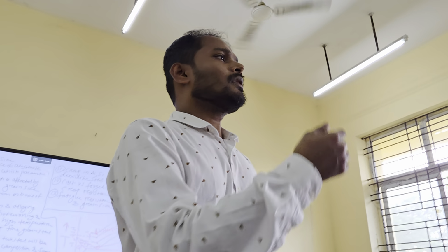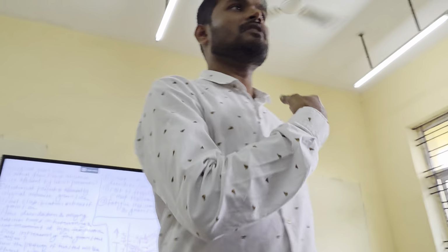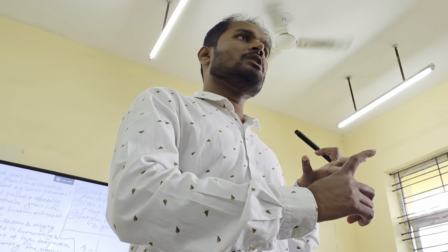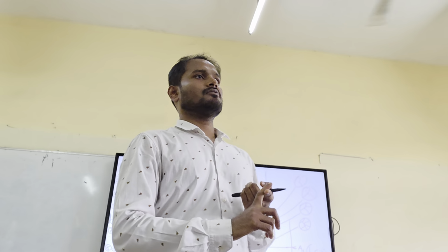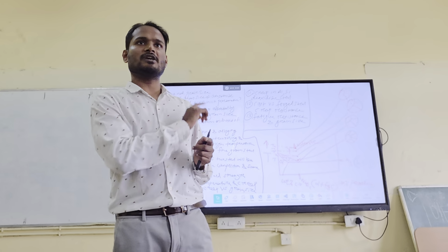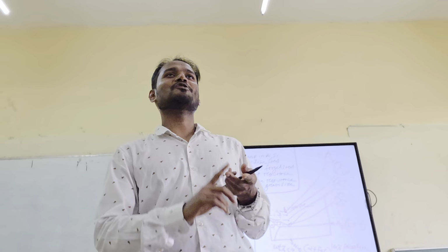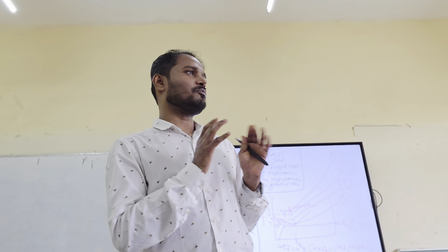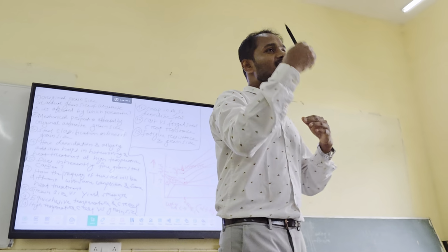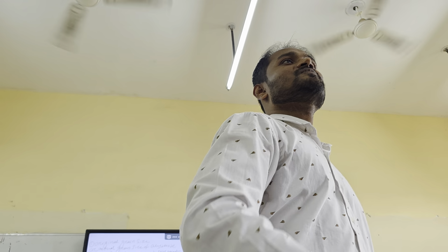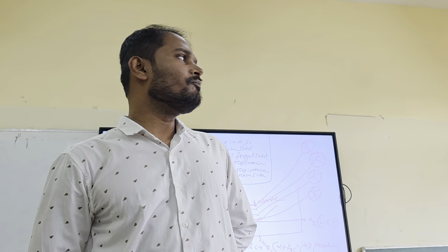Anyways, my point of view is hardenability is a very important property, and that property is affected by the grain size also, austenite grain size. So austenite grain size will affect the strength, it will affect the machinability of the steel, it will affect the hardenability also, and also toughness. These are the 4 important mechanical properties affected by the grain size of the austenite. And we always need good hardenability, good machinability, good strength, good toughness. All should be in a good shape, or in a high value, right? So that is the need we are doing heat treatment again, to improve the toughness, to improve the strength, to improve, somewhat, so not exactly soft, it should be intermediate actually.